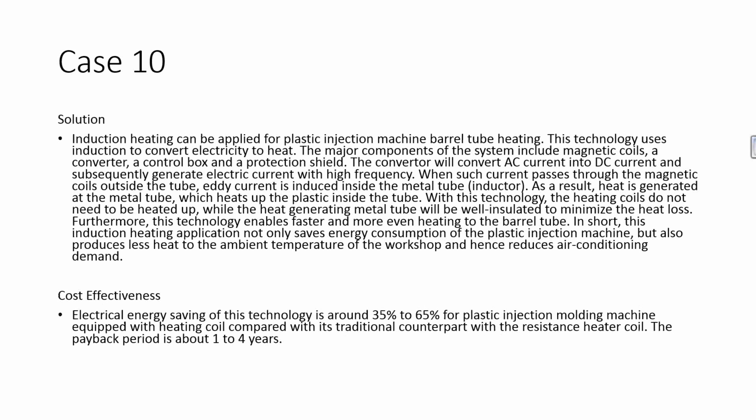The solution for this, induction heating can be applied for plastic injection machine barrel tube heating. This technology uses induction to convert electricity to heat. The major components for the system include a magnetic coil, a converter, a control box, and a protection shield. The converter will convert AC current into DC current and subsequently generate electric current with high frequency.